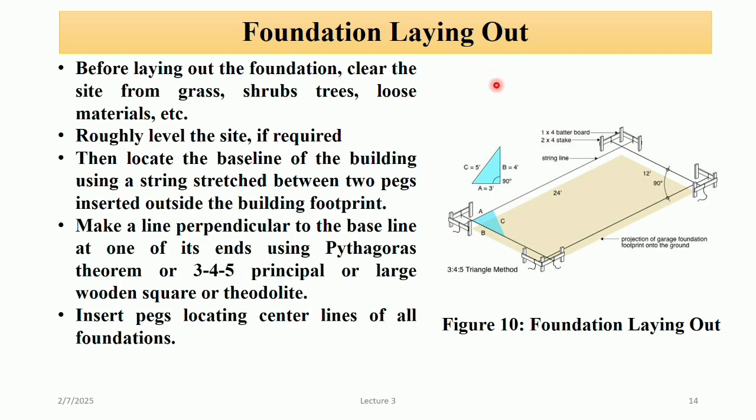Foundation layout. Let's suppose that we select a site for constructing a building. Now we have to construct the foundation for this site. For this we have to clear the site of grass, shrubs, trees, loose material, etc. Then if the site is not level, we have to roughly level the site. After that we have to locate the baseline of the building by using a string stretched between two pegs.